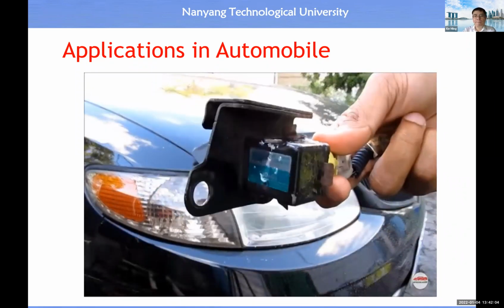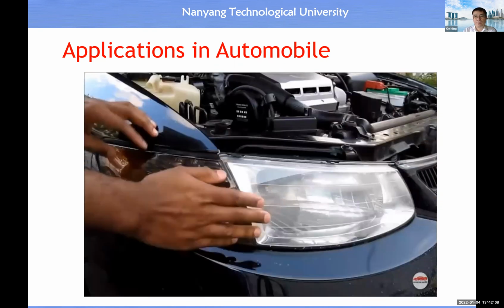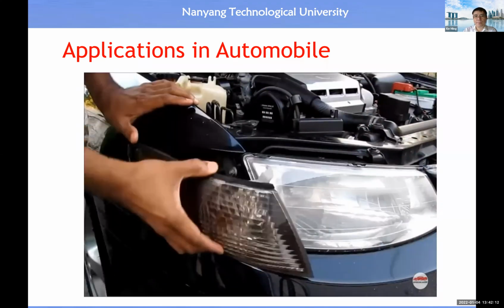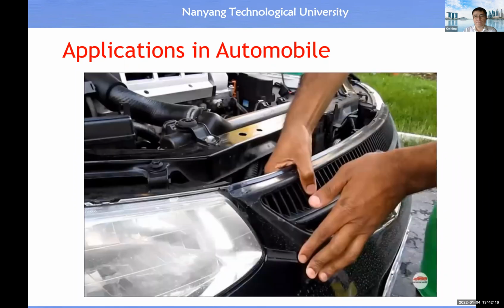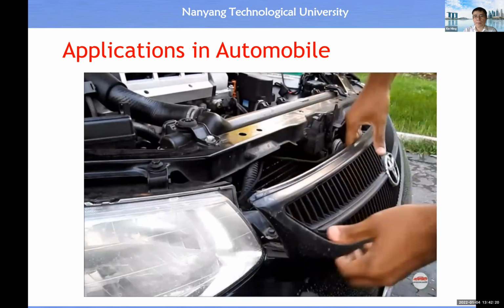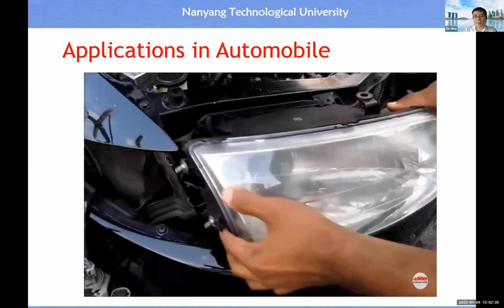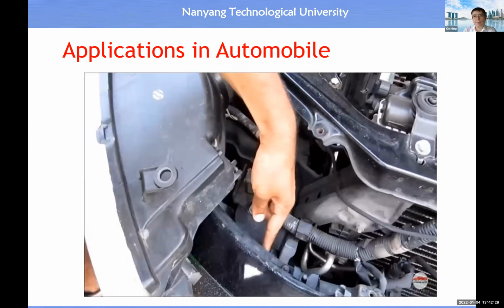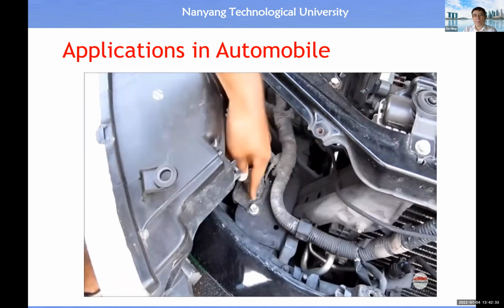On these Toyotas, the airbag sensor is usually bolted to the radiator cradle. Here's how to access the airbag sensor under the headlight. We remove the side marker, and remove the headlight bolts. I'm going to remove the bolts for the grille, and pop the grille off. Pull out the grille, remove one more headlight bolt, and then remove the headlight from the car. This here is where the frame connects to the bumper rebar. This is the airbag sensor. To remove it, there's one 12mm bolt and one electrical connector that needs to be removed.